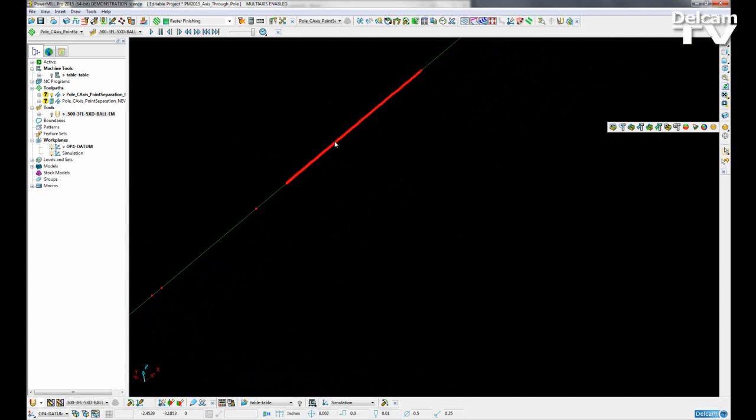So what we need is a method of clearly defining the position of the pole within PowerMill. Behavior of the toolpath around the pole should be definable to give the best results. What we want to do is maybe avoid the pole or force the tool axis through the pole. If we have a machine tool defined, then that should be used to determine this behavior.